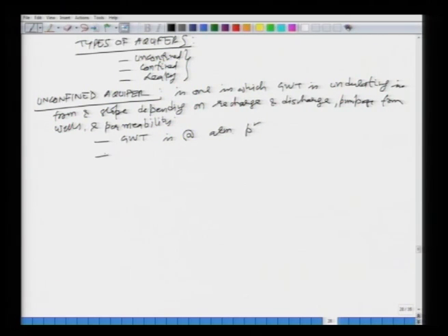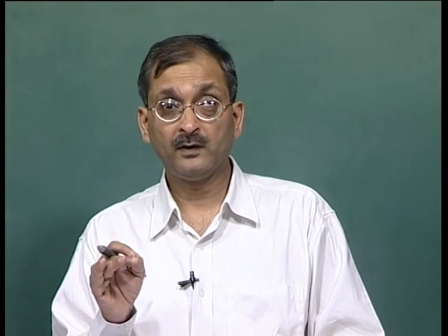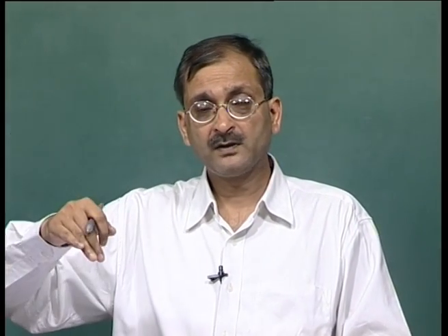The other one is that the rise and fall in the groundwater table corresponds to change in storage in the aquifer. This is important. Why? Because an unconfined aquifer can be recharged from the top, from the ground.